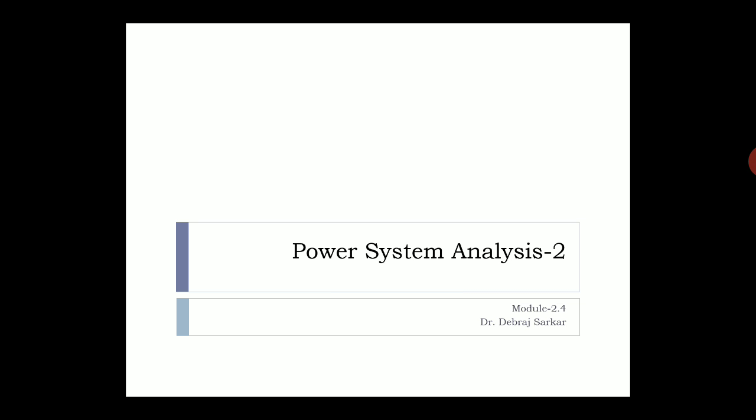Previously we have discussed two different methods of solving power system equations: the Gauss-Seidel method and the NR method. Both of these methods are long and might take a lot of memory for the computers. Most of the time that amount of memory is not available, or it will take a lot of time to solve. So some other methods should be prepared. These methods are not accurate, but they do the job. They are called the decoupled load flow.